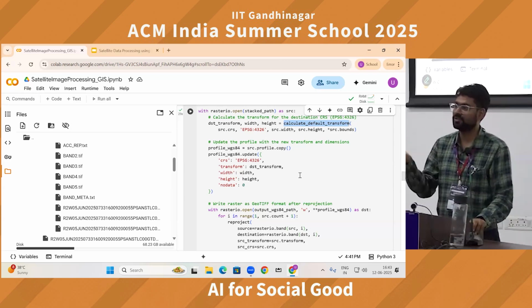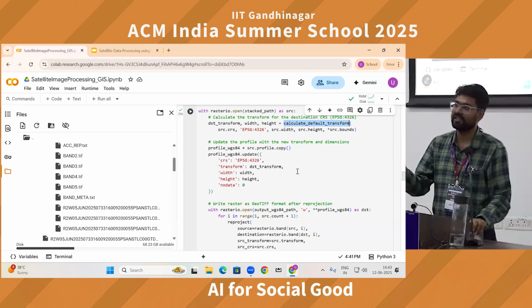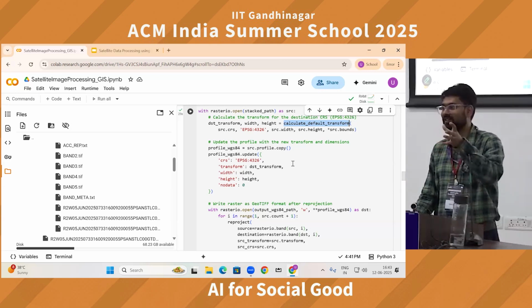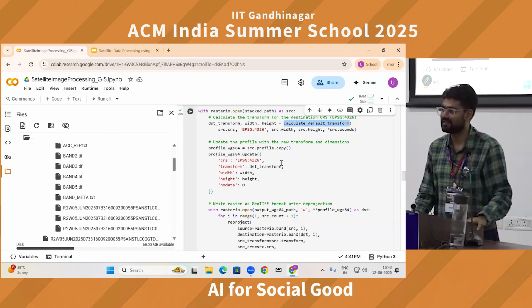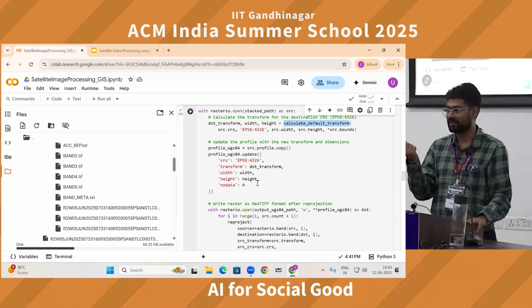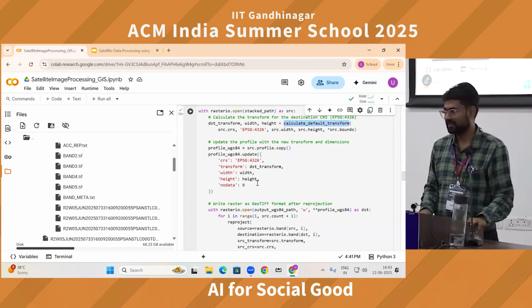Okay, that is also one of the capabilities of GIS software, which is not typically given in computer vision libraries, where you have to do something. Let's say if you want to calculate the statistics, finding the statistics using rasterio on geospatial data is easy because it understands no data values. But in case of the common computer vision libraries, you have to write some code explicitly, or you have to filter it for generating the statistics.